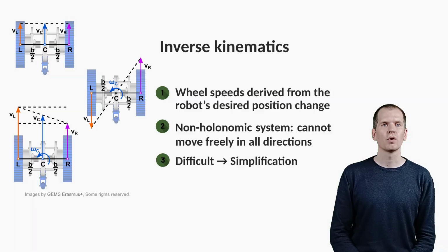And third, linear motion and rotation. For each of these cases, we can easily calculate the required velocities. Movement from point A to point B is composed of many instances of these three cases. At this point, we have enough information about kinematics for a mobile robot with differential drive.